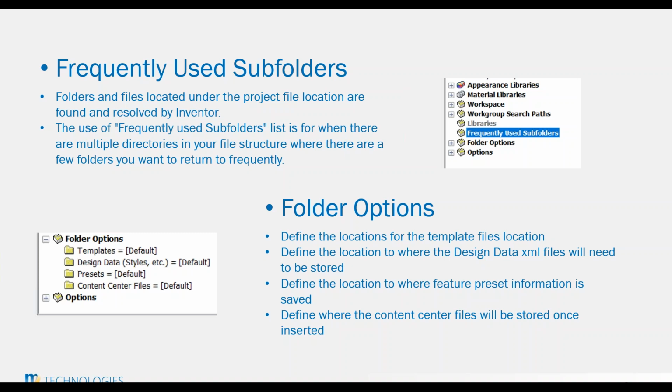If you don't set a template folder, again, it's going to use the default, which means every project file you create will have the same templates. If you have a customer, or maybe multiple customers that you need to produce different types of drawings for, then it might be worth your while to come in here and set different folders. Again, when you activate the project file type, the template folder will then be set per this setting.